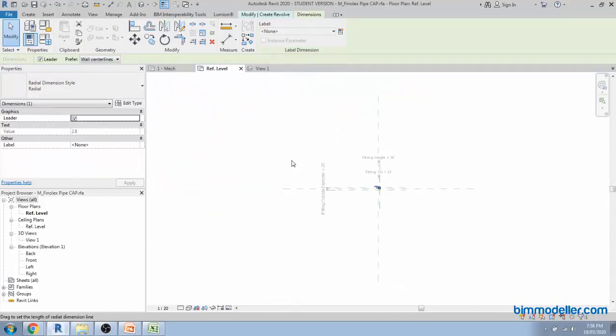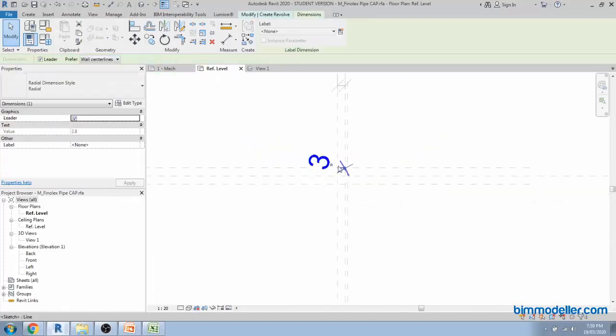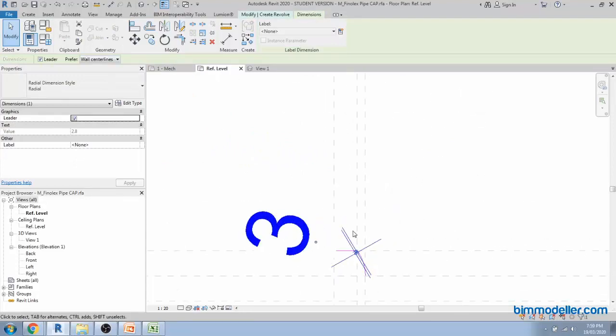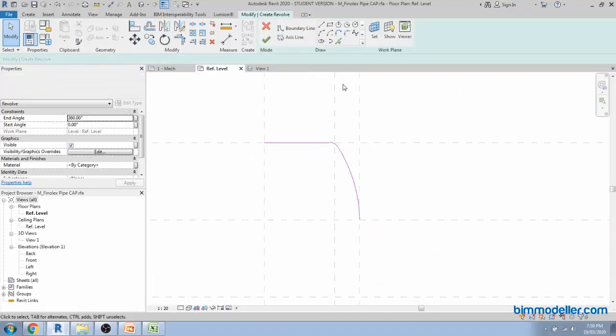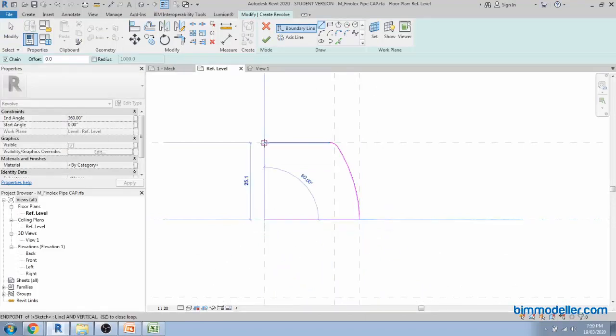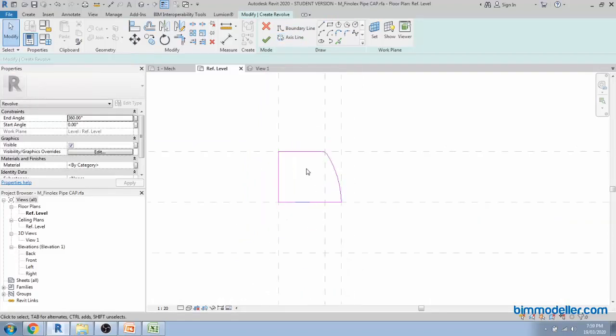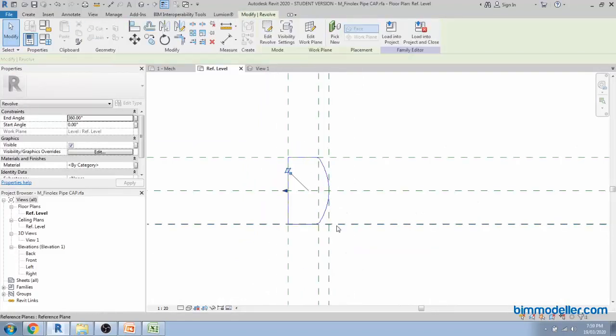I have to find the lock symbol and lock it. It's not showing at all, so let it be simple, and we'll be able to create a line from here to here. If you need, you can lock it. I hope it is not required by default. It will be aligned, since it's a sweep, automatically it's aligned.